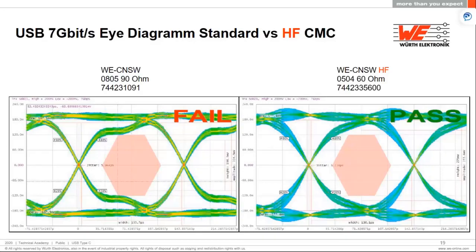When you use a high frequency component, which are more suitable for higher speed designs, you'll see that we have enough slope for the rising and the falling edge, and the signal is not at all disturbed by addition of these components. So that is why it is important to select the common mode choke in accordance with what speeds we are trying to achieve and what frequency we are working at.